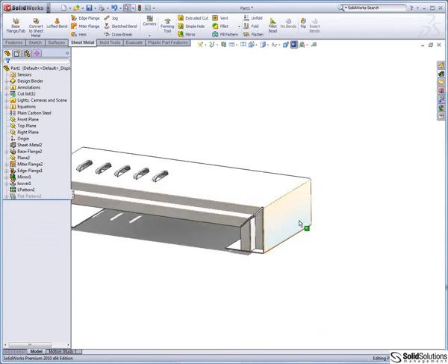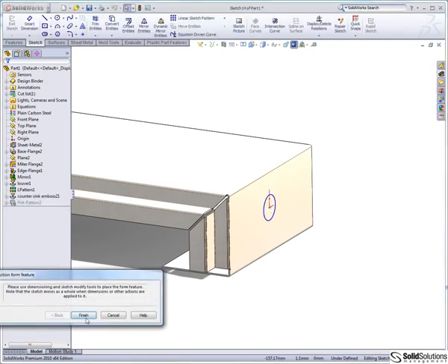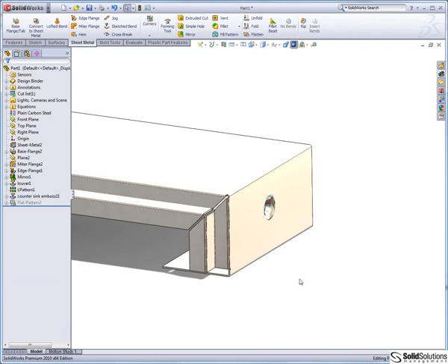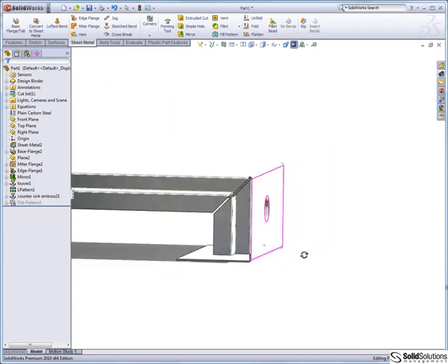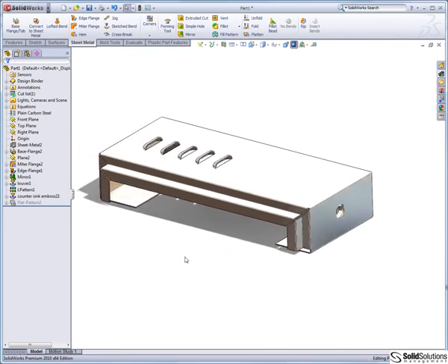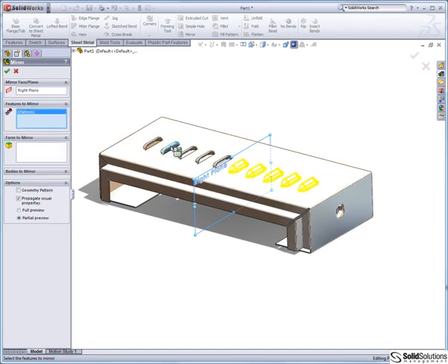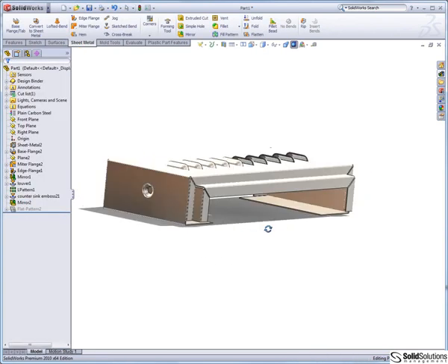Another one in the standard SolidWorks design library is just a little recess, just an emboss. And again, just drag and drop. And it's just a sketch, so we can add dimensions to place that if we choose to. Just want to mirror those across to the other side. It doesn't matter that we've got features on either side of the component. SolidWorks just mirrors them regardless. So if we just choose the central right plane there, we can just choose the features that we want to mirror, and it just mirrors both across onto opposite sides, again giving us the preview.